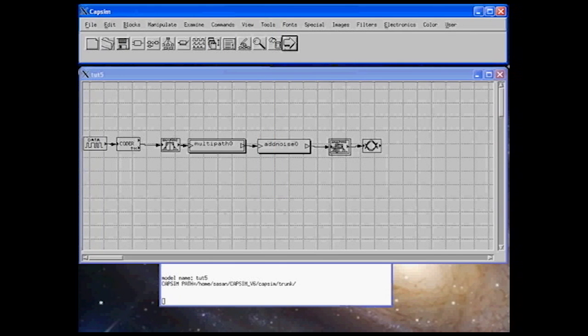In order to demodulate the received signals, notice that after match filtering, we have to sample the filtered signal at the peak and take the sampled values at the peak only and discard all the other samples. Therefore, we have to do a sampling and a sampling rate reduction, a decimation. After we do that, we have to pass the samples through a slicer or a decision device and then recover the original bipolar signal, plus or minus 1, and compare it to the original one to get the bit error. So that's what we're going to do in the following steps.